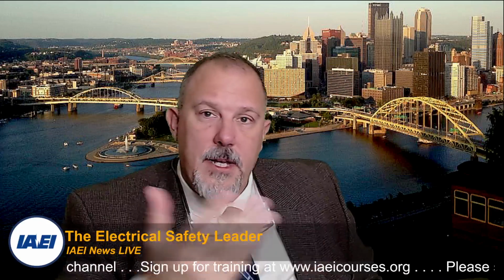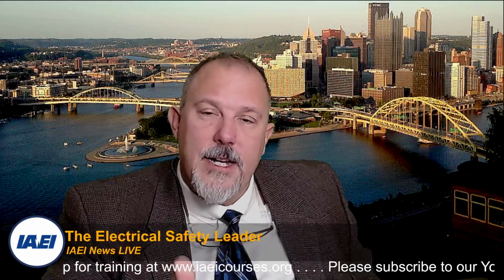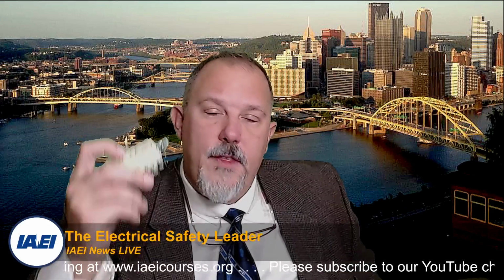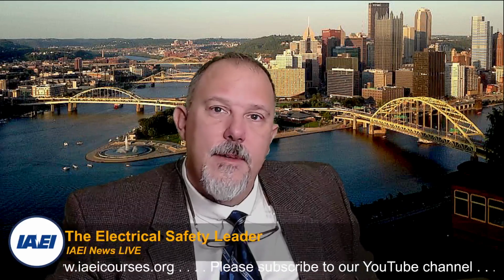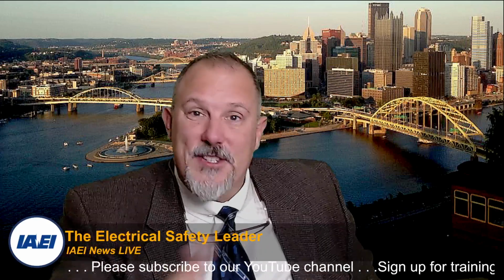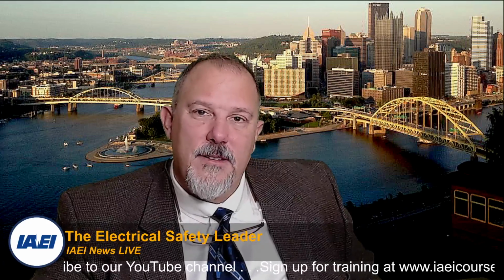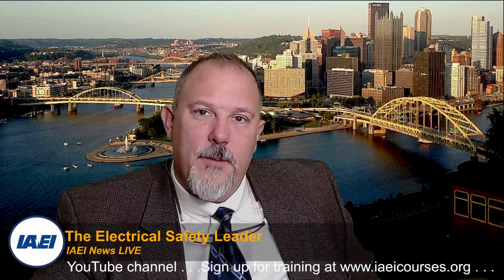Then plug something in downstream and show that inspector or show the homeowner it's not protected because this is open. And then close it, power it up, plug that light back in. Now you've verified presence and absence of voltage. It's no different than testing for absence of voltage from a 70E perspective.